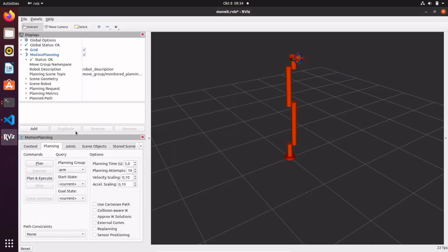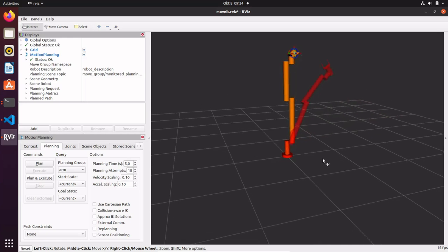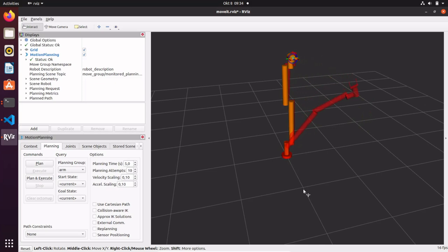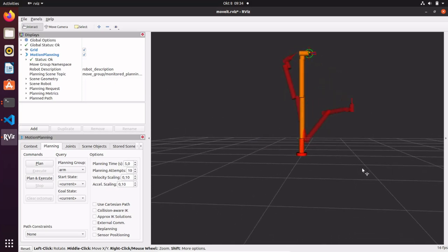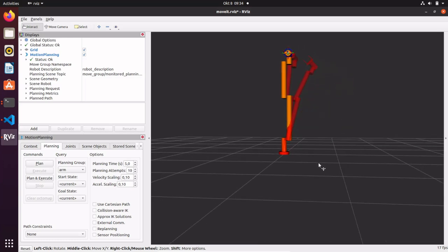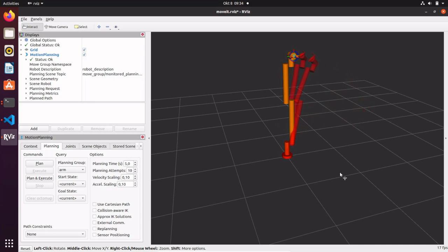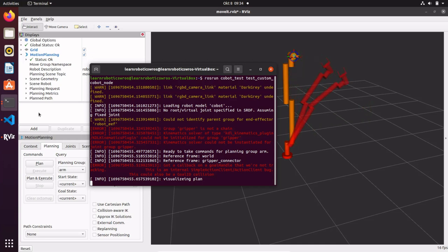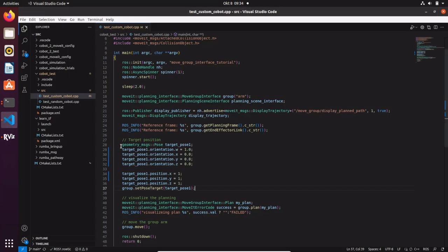And I can understand if you struggle to imagine a quaternion, because you are used to orienting your TCP with respect of the yaw, pitch and roll. So the scope of this video is to understand how to orient your TCP without making mathematical calculations, with a visual approach and, in my opinion, a very intuitive one.